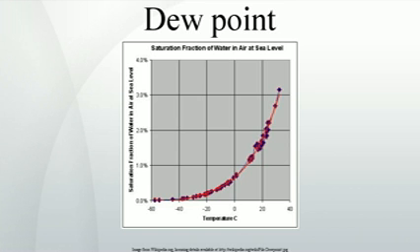At a given barometric pressure but independent of temperature, the dew point indicates the mole fraction of water vapor in the air, or, put differently, determines the specific humidity of the air. If the pressure rises without changing this mole fraction, the dew point will rise accordingly. Reducing the mole fraction, that is, making the air less humid, would bring the dew point back down to its initial value. In the same way, increasing the mole fraction after a pressure drop brings the relative humidity back up to its initial level.